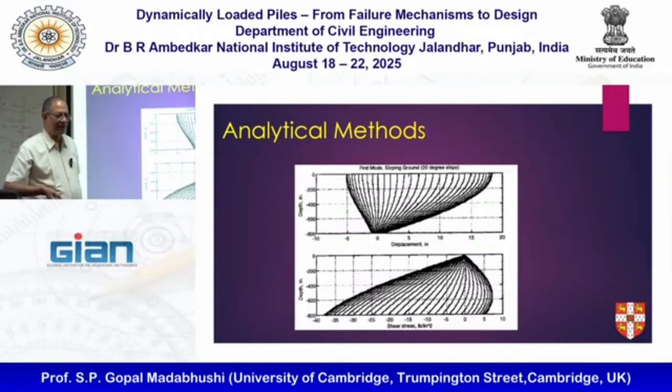So obviously what they mean here is pound force per square inch. We can sit down and convert all this into kPa quite easily. So 1 pound is 2.2 kilos, so it's about 22 newtons, and inch is 25.4 millimeters. Convert that into meters, and you can convert that into kPa with a factor.